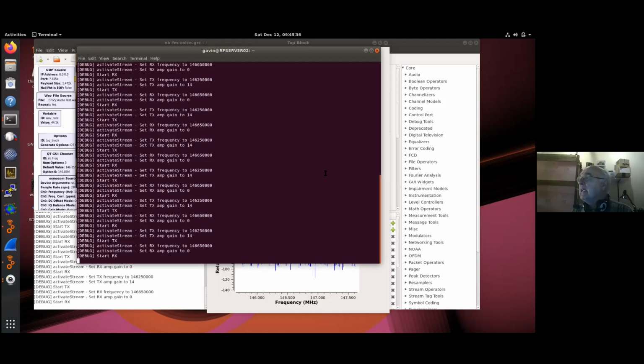So first, the HackRF. I mentioned early on that I chose it because it could transmit, but that was an uninformed decision. It can transmit, but only 10 milliwatts. In order to transmit anything and use it for amateur radio, you've got to get up to 10 watts. So 30 dB of gain there. And so that was why I had to go with cutting the trace and bringing out the transmit natively and so on.